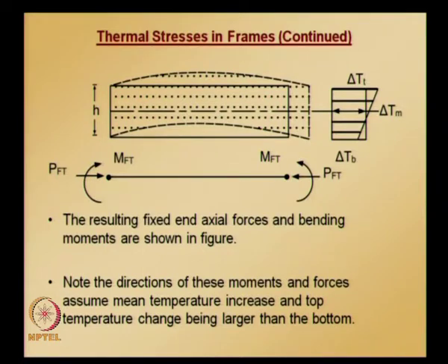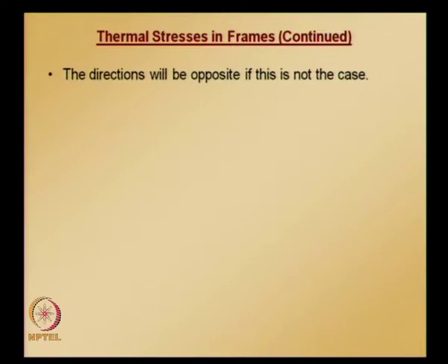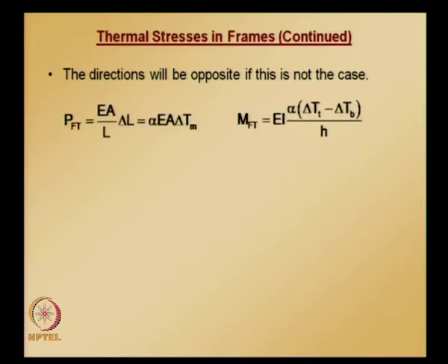Okay. So this is what is pointed out there in the slide. The direction will be opposite if this is not the case. So now let us see what these values are, how we get them. In the figure we have indicated, or we have seen, how these forces, axial forces and bending moments are acting, fixed end forces and bending moments, but how to compute those from the elongation and the curvature that we have.